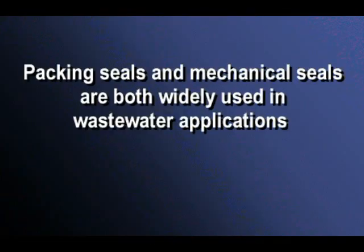Packing seals are simple and economical and are therefore used widely in dry installed wastewater pumps. However, since leakage rates must be checked and adjusted, packing seals are not suitable for submersible pumps. Mechanical seals are commonly used in submersible applications as well as in many dry well installations.